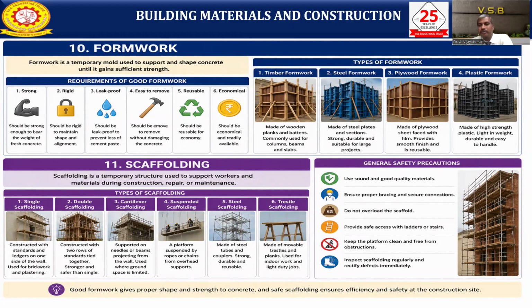It should be easy to remove after the concrete is completed. After the curing time, we need to remove it easily without damaging the concrete. After that, the formwork can be used again. When we reuse it, it becomes more economical. It should be economical and readily available. There are different types of formwork normally used.